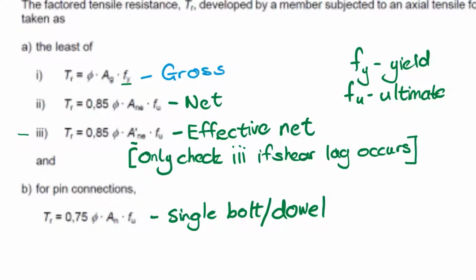And this actually failed at about 660 MPa, because one thing you must remember from earlier lectures, your specified steel strength, for instance a 355 MPa steel, is the minimum with a certain percentage probability that's allowed to land on site. The average material strength should be above this. So this is specified as a 550, but what we actually tested was 660.